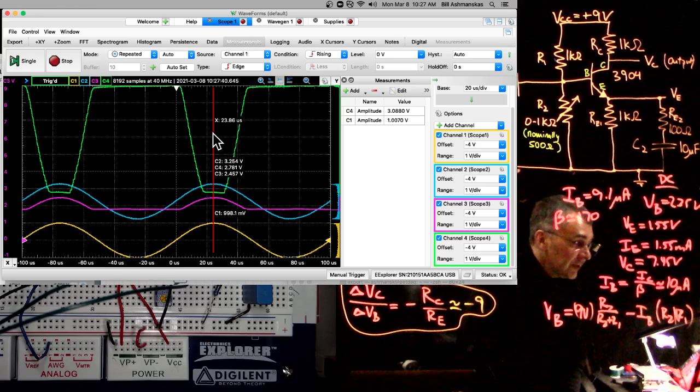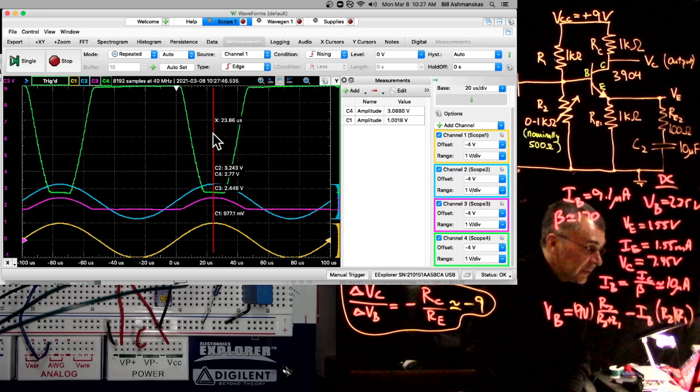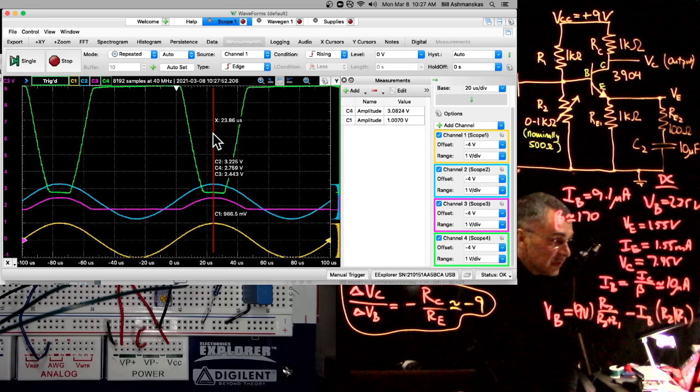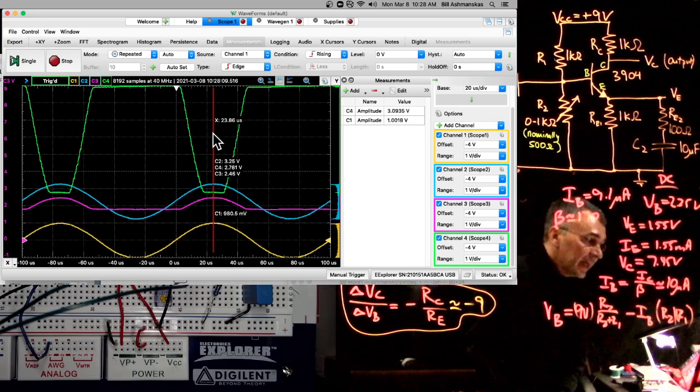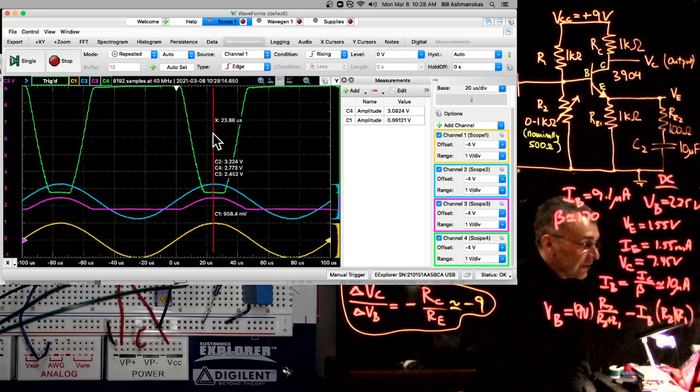And then you can see that during saturation, the collector is somewhere in between the emitter voltage and the base voltage. So basically, VCB has gone negative. If we looked closely, we would see that now there is significant base current. So in saturation, you no longer have this nice factor of beta between the collector current and the base current, and you no longer have negligible base current. Wiggling the base no longer directly affects the collector so easily. So basically, the collector current is as on as it can be.